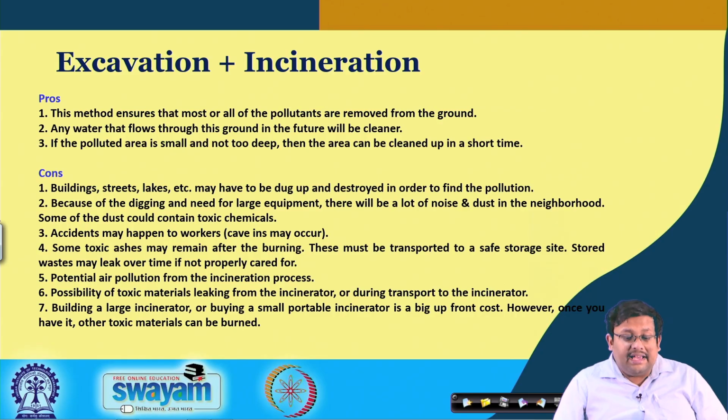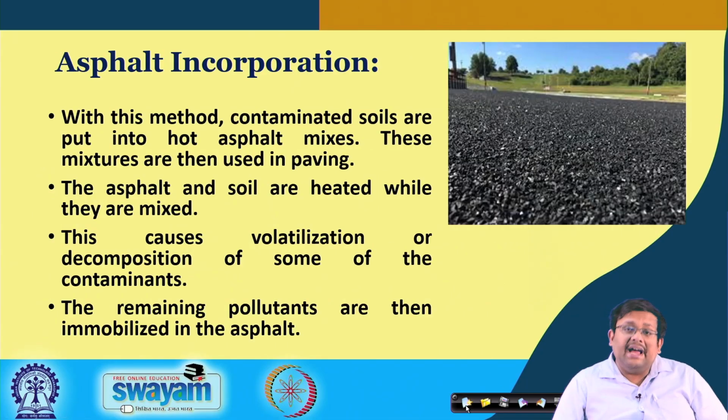We have finished excavation and incineration, and the next method of ex situ decontamination is asphalt incorporation. With this method, contaminated soils are put into hot asphalt mixes, and these mixtures are used basically in paving, as you can see in this picture. The asphalt and the soil are heated while they are mixed, and this causes volatilization or decomposition of some of the contaminants.